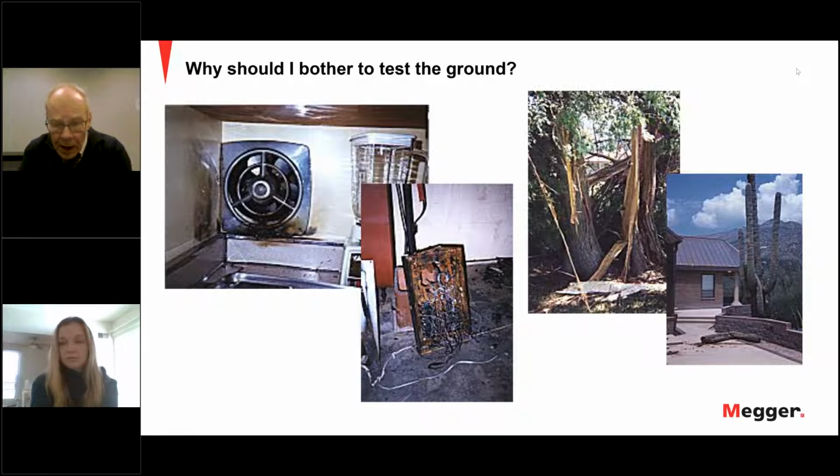That varies a lot with the environment that you're in, but certainly some environments are highly conductive, and so you can lose your grounding electrode, and you don't see it. It's buried out of sight. You see the wire going down into the ground, and you think everything is fine, but it's not.